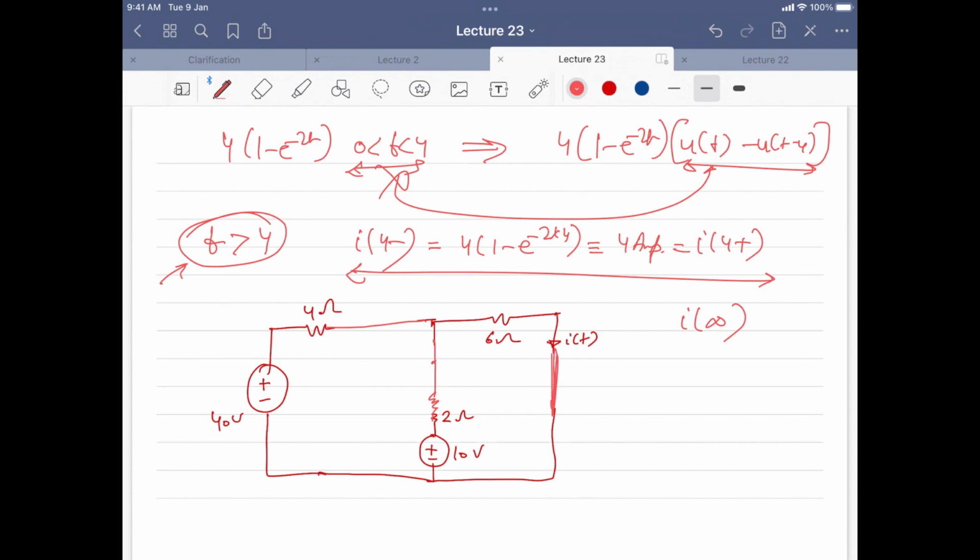And then we will use nodal analysis to calculate the voltage. What is the value of voltage here? 30 by 11, right? Yes, sir. No, the voltage will be, sorry, 180 by 11. Right. So the voltage is 180 by 11, and the current which will flow here at infinity is 180 divided by 11 times 6. So that will come out to 2.727. This is the current that you will get.